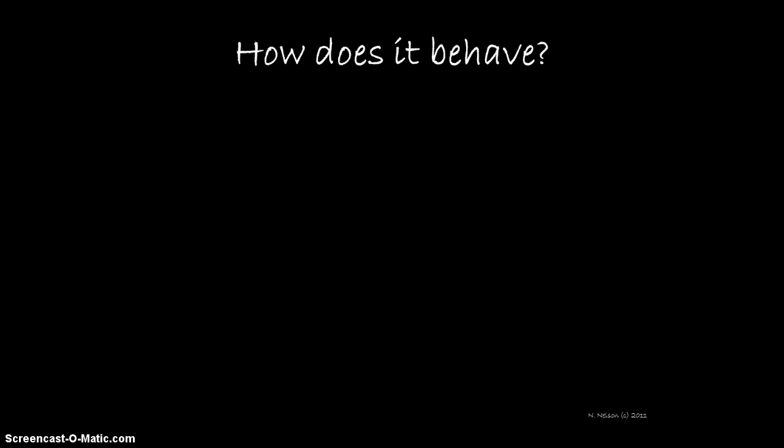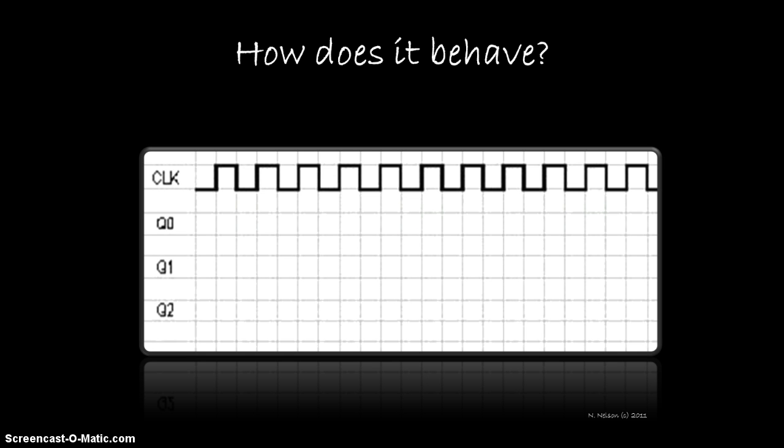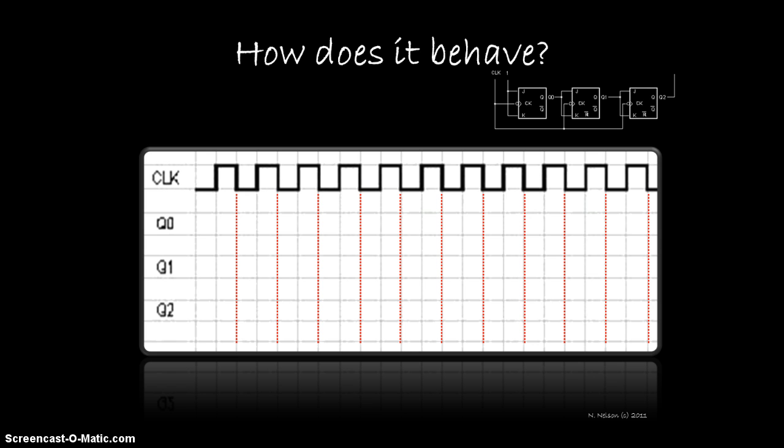As you've done before, you can determine how the system behaves using a timing diagram. First, mark in the falling clock edges. Remember that the output transitions can only occur at one of these edges. Knowing that Q0 toggles each time the clock is high at a sample point, you can mark in the waveform for Q0. Show the propagation delay, since it will help you determine the state of Q0 when doing the Q1 waveform.